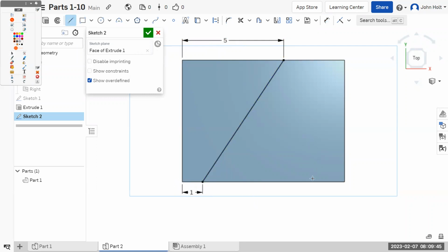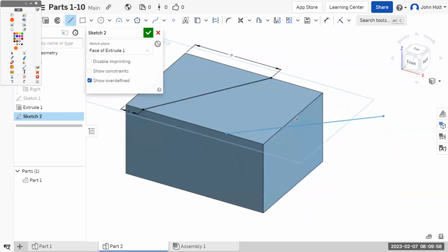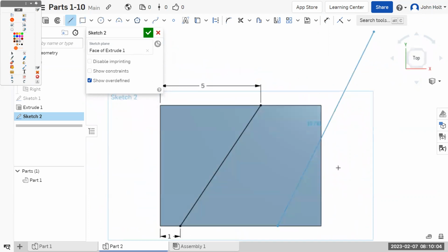And then the other line connects the same thing from the bottom edge to the right side edge. And actually, we can snap it to the center point here, because what we're trying to go is 3 from the front and the whole thing's 6. So you can just snap to that center point. Save you a second.